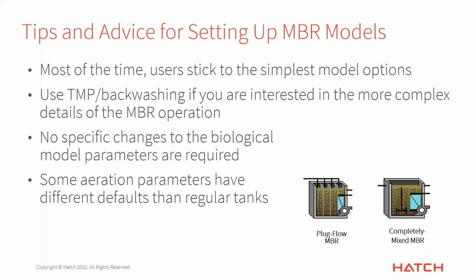But one thing that is different is that some of the default parameters in the aeration model are different in the MBR than they are for regular tanks. So you'll find that alpha is different and the oxygen transfer is different. And you'll find different values for the regular biological air versus the scouring and cleaning air. We took quite a bit of effort to do that. I think we also tuned the DO controllers a little differently, trying to keep them a little more realistic for the types of technologies that are going to be used for those two particular purposes.